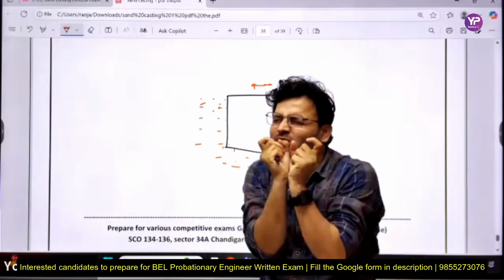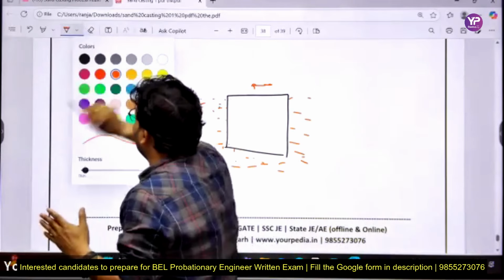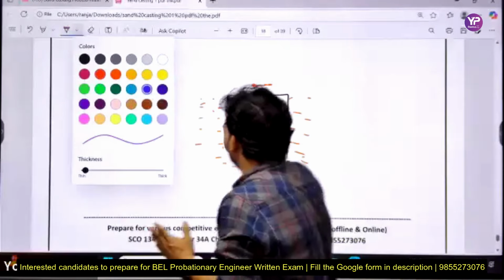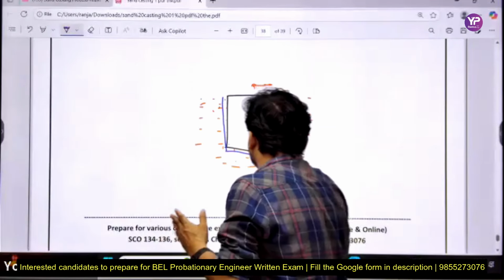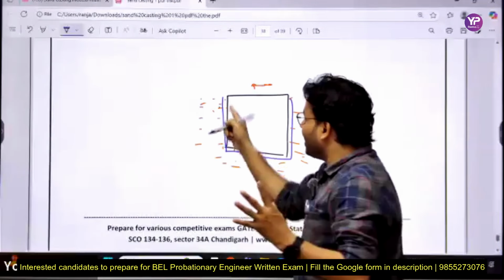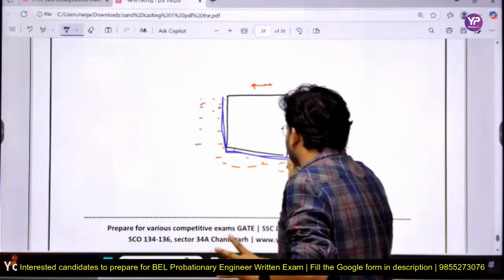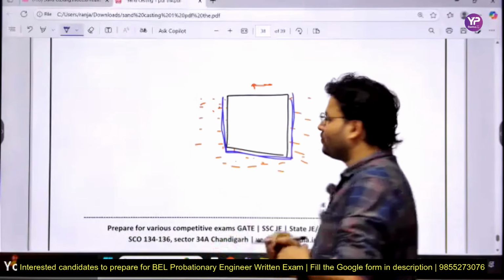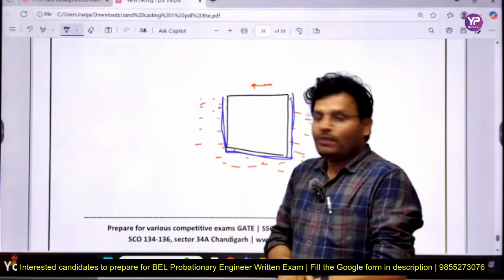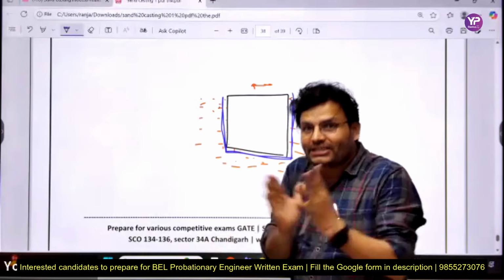Just listen to one thing, my dear friends. Actually, the product that I will get, because I have to shake a little bit, the size will be something like that. If you require that much amount of cavity, or that much size of product, you have to make the pattern lesser in size.